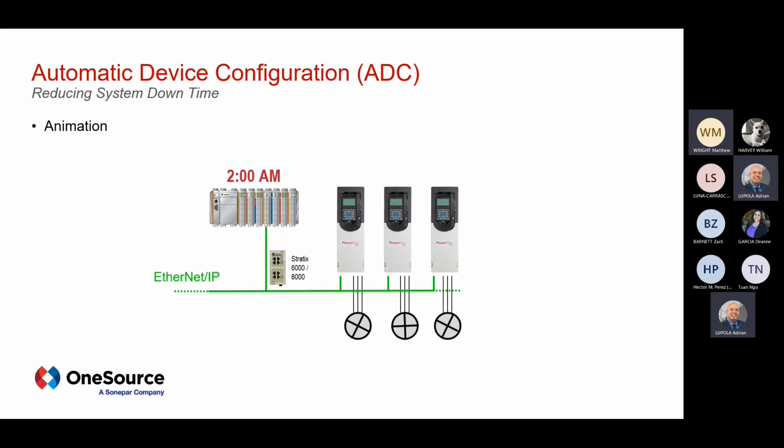The second thing is the controller is going to look at the firmware of the drive. The firmware of the drive has to match the firmware that's set up in the controller. And if it's not, you can set up the firmware supervisor in the controller and load the firmware file of the drive on the SD card. The firmware supervisor will then automatically flash the drive with the firmware that is loaded on the SD card.